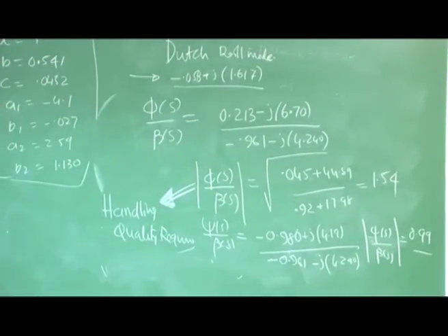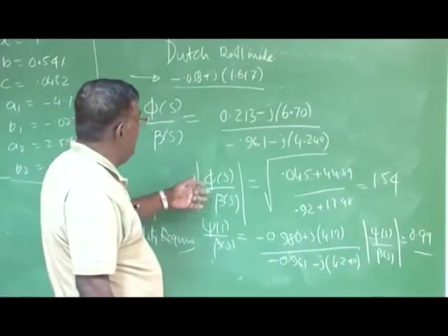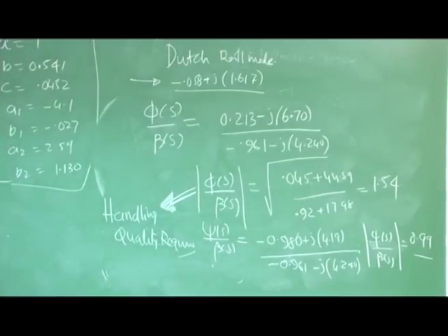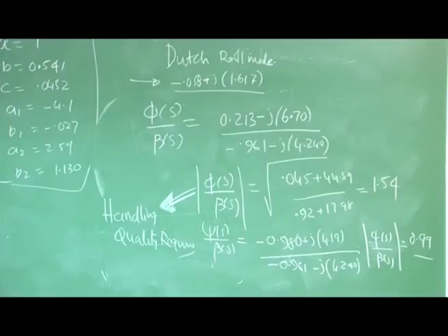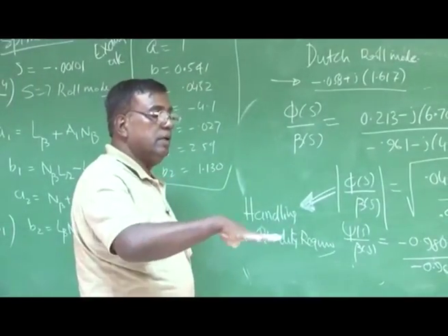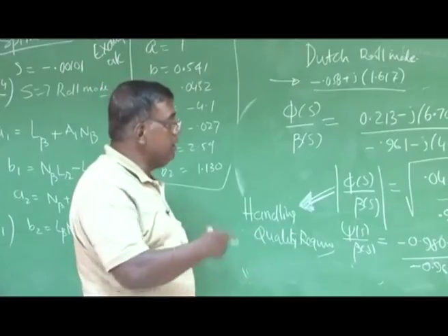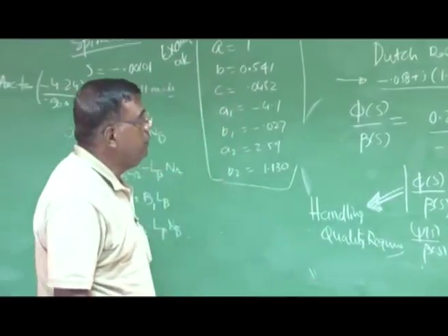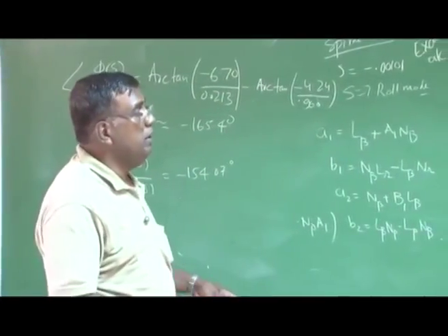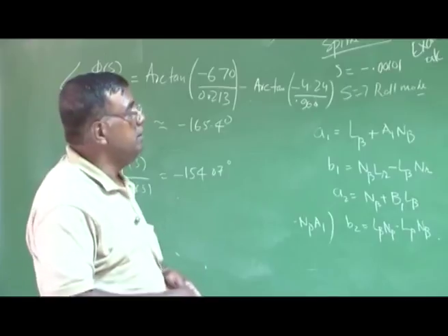From the handling quality requirement, we try to have this ratio as low as possible to get a scale for acceptance for Dutch roll excitation. That is extremely important. If the airplane is banking and sideslipping and this ratio is very, very high, then you can understand Dutch roll oscillation acceptance will not be approved. It should be as low as possible, right?